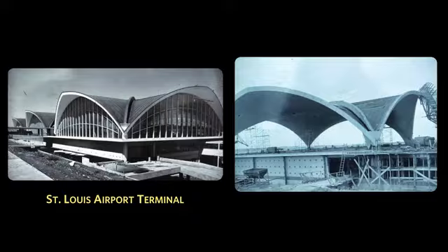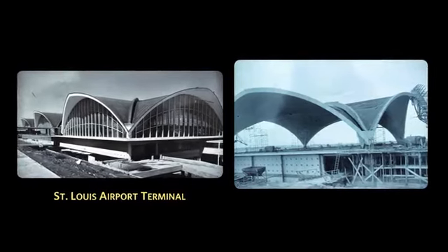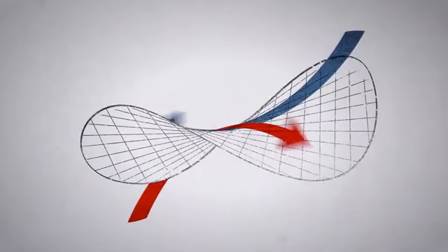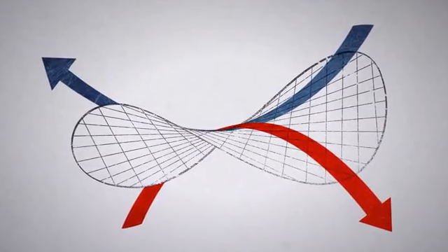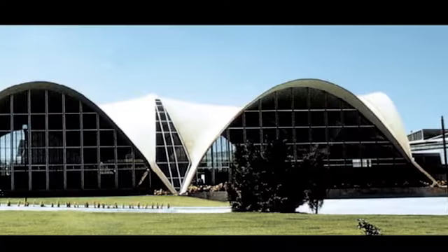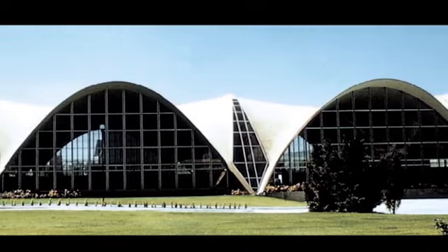But would it have been possible to design this type of vaulted structure without ribs? The answer to that question is both yes and no. If we use intersecting barrels as done here, the ribs were needed. But what if we used intersecting hyperbolic paraboloids instead of barrels? It's a different shape, the hyperbolic paraboloid, that has curvature in 2 directions and adds stiffness. And that is indeed what Félix Candela did.